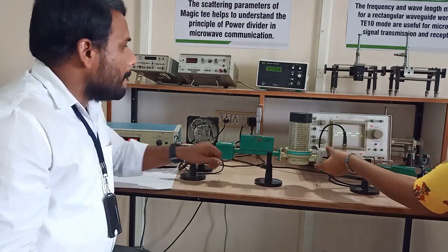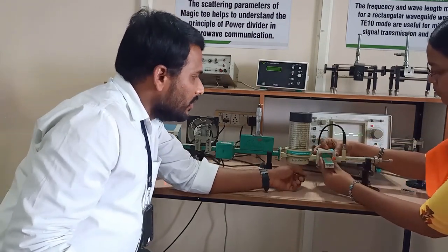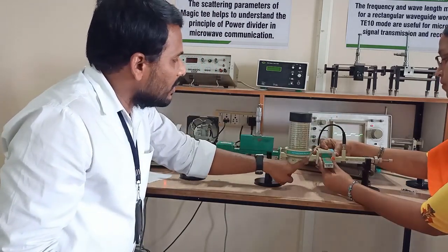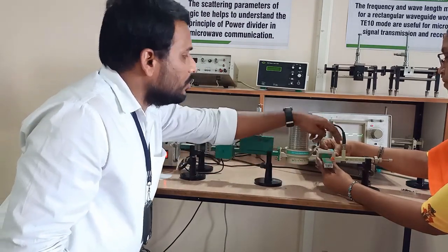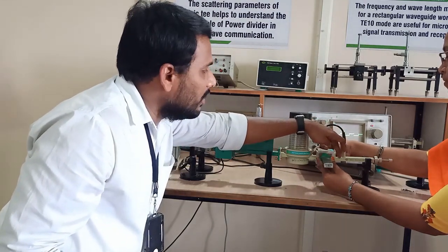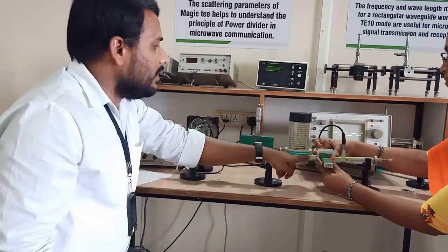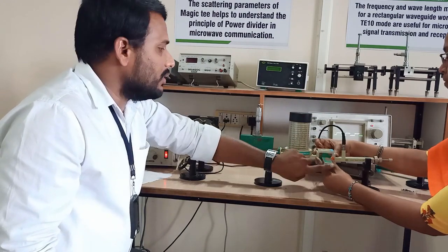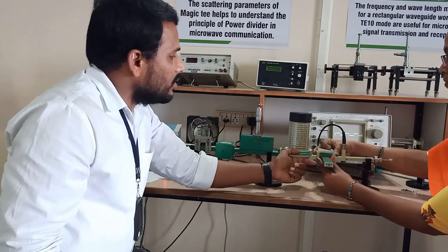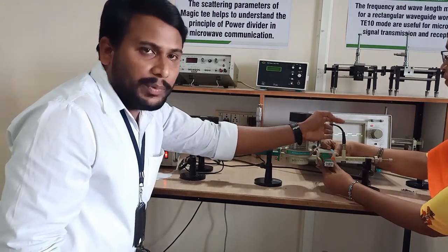Okay? See, check it here. See the signal? Now we have connected the circulator: port 1 is connected to the frequency meter, and here it is port 2. Port 2 is connected to the detector mount, meaning we are taking the output at port 2 by using the detector mount, which is connected to a CRO. On the other side, port 3 is connected to the matched termination. It completely absorbs the energy, so there is no leakage of power here. Whatever energy reaches port 3, the entire energy goes towards port 2, the output port.